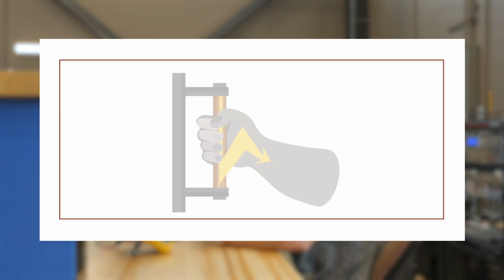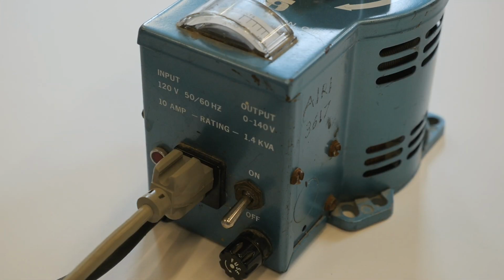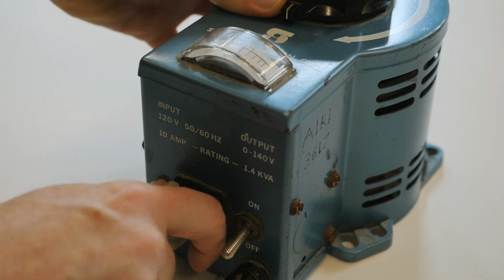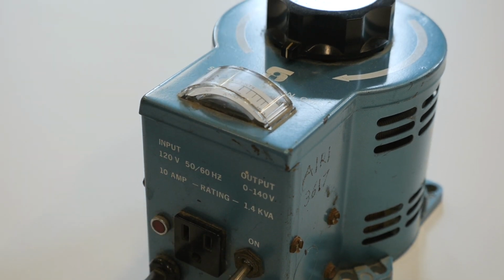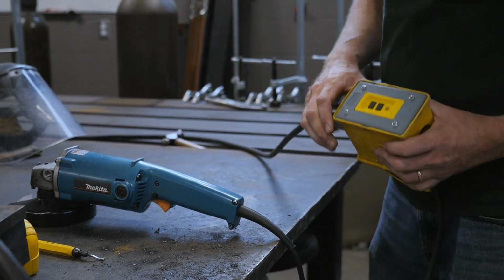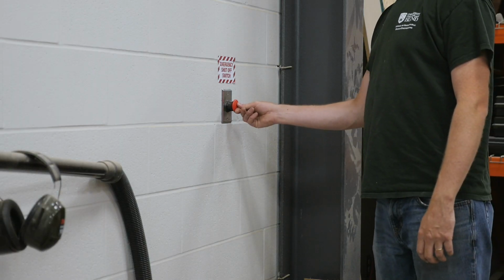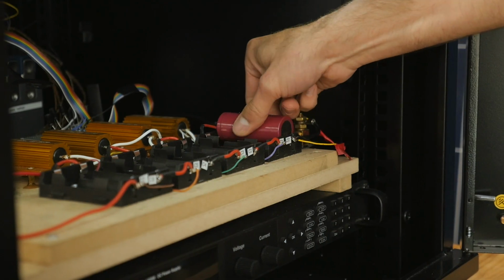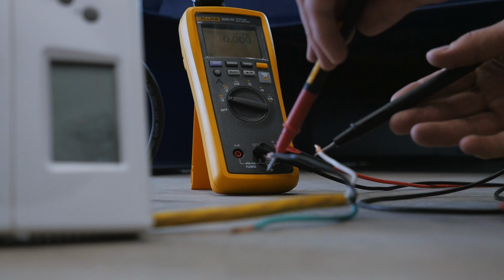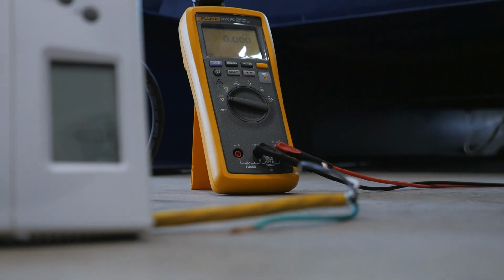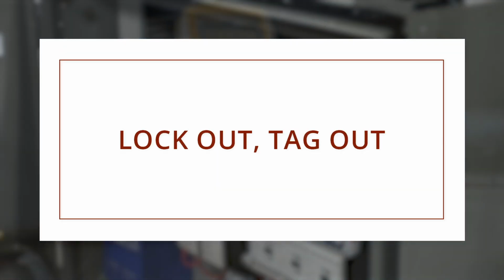To avoid an electric shock, you must not become part of an electric circuit. The safest approach is to always disconnect the power source before working with electrical conductors, whether by switching off a disconnect, turning off the breaker to the circuit, or removing the battery. You should confirm that the wiring or instruments you are working with are not energized with a meter before making contact.